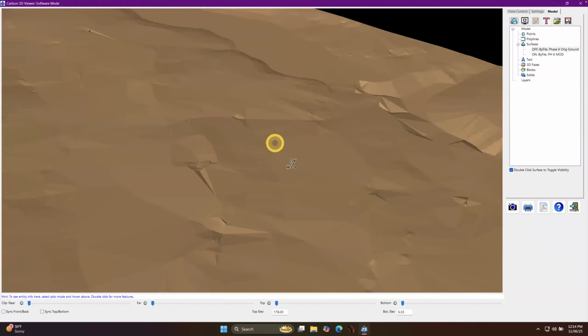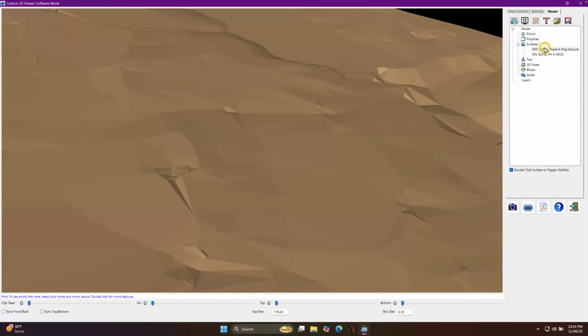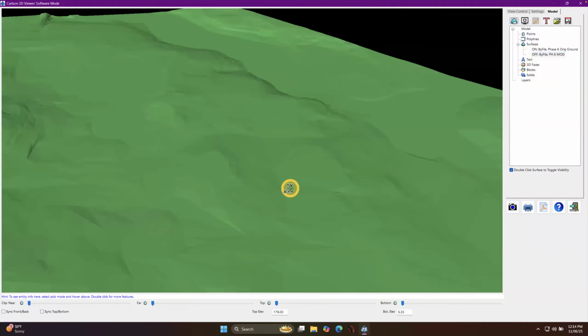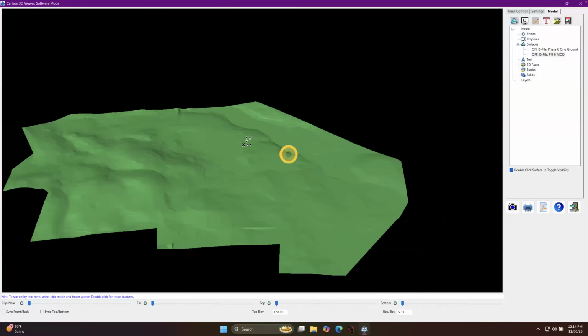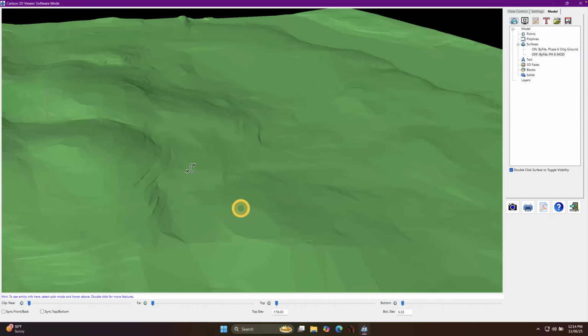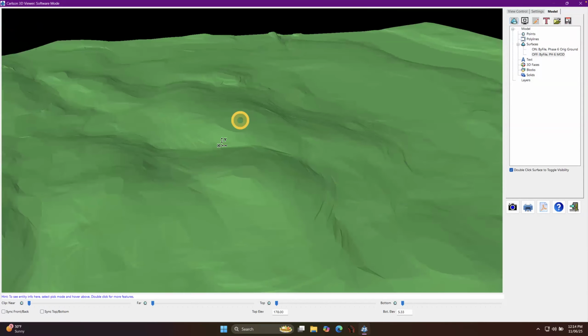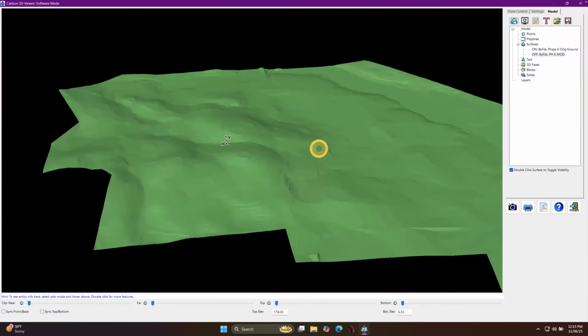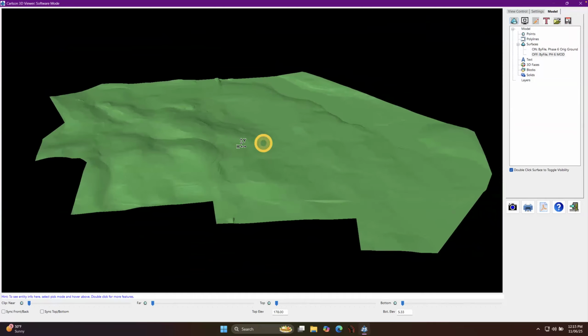So again, just something that I notice. Let me turn that on and that back off. That's just something that I notice from years of working with this kind of data, how I can tell that something's been done. I look at that and it immediately tells me somebody built this from contours. Now, there may be a part of the world that's actually like that, that these are all sawed off flat pieces of hilltops. I doubt it, but without knowing otherwise, you can't make the assumption.